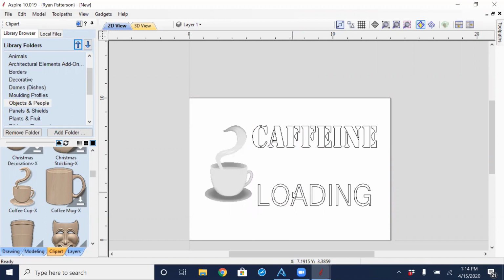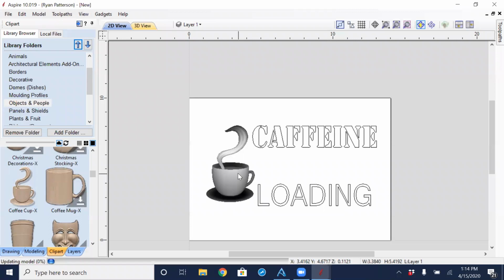And just moving and shifting things around. You could also shift by selecting the object and using the arrows on the keyboard. Sometimes that is a way to only be able to move in one direction. I use that one quite a bit if I have the Y placement just right, but I want to play with the right and the left side of it. So I might select it and use the right arrow or the left arrow only to move back and forth.